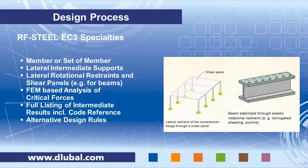RFEM includes such a FEM-based analysis inside the module RF Steel EC3, and for any load case, for any loading situation, for any members or set of members, it automatically does this numerical analysis in the background. So you have a very good result for these really important design values for your Eurocode design.